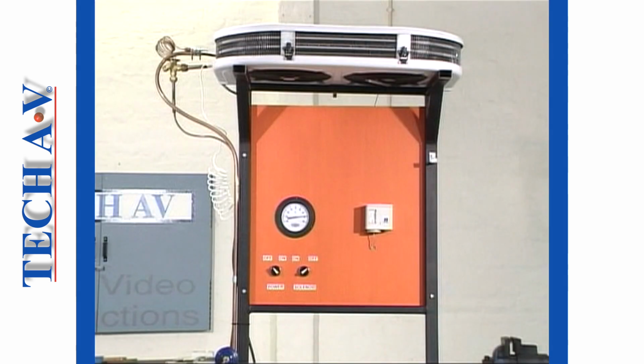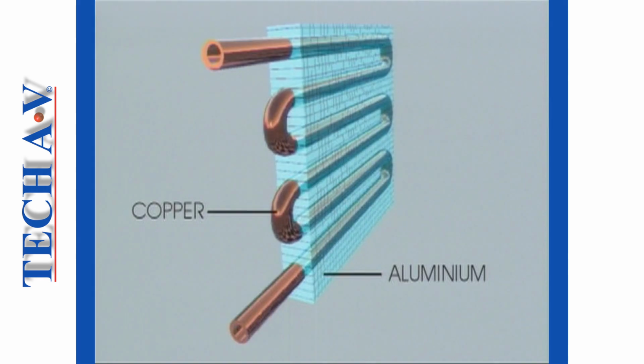This evaporator employs air draft fans to assist with the air circulation over the coils of the evaporator and in the cooling space. A feature of evaporators and condensers is that they are both made of metals, such as copper and aluminium, which possess good thermal conductivity characteristics.